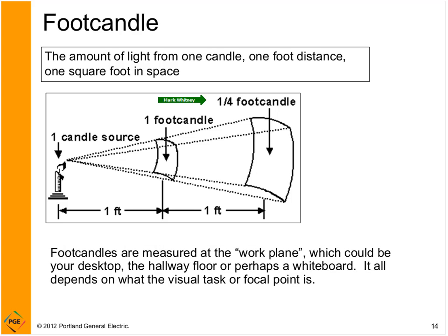So the Illuminating Engineering Society publishes a lighting handbook, and they group light levels in categories. Just as a point of reference, orientation and simple visual tasks, just getting around, could be less than 1 up to around 20 foot-candles. Your common visual tasks, like reading, are going to be in the range of 30 to 75 foot-candles. And then you have special visual tasks that could be inspection or all the way up to brain surgery, and that could go up from 100 to about 2,000 foot-candles.